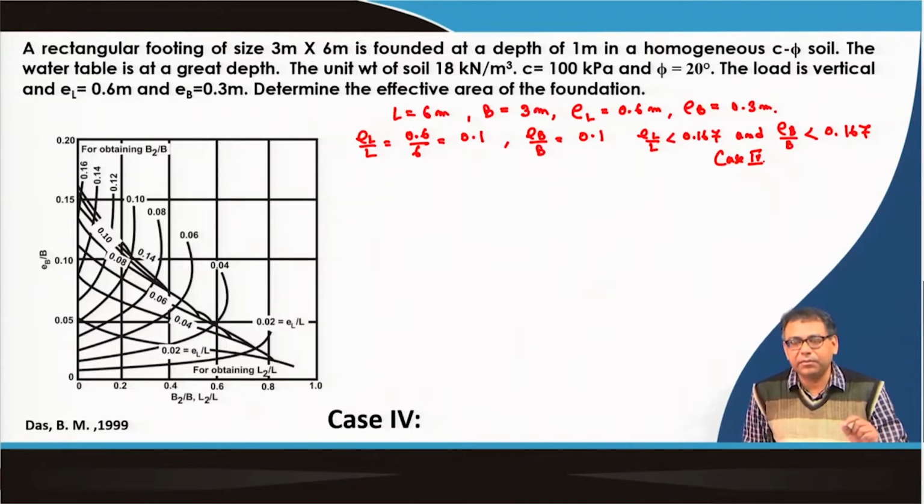But in case of Terzaghi, this option is not there to incorporate this loading eccentricity. But remember that when you use the other methods, then you calculate the correction factor according to their suggestions. Okay? That means, in some cases you have to use B and L, and in some cases you have to use B dash and L dash.